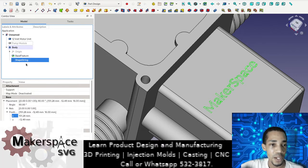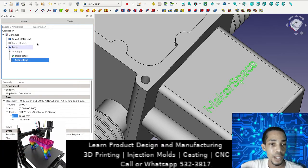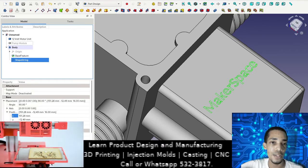Okay, continuing now. I have the shape string attached to this body, and I want to extrude it into 3D space, so I go ahead and click on Pad Selected Sketch.